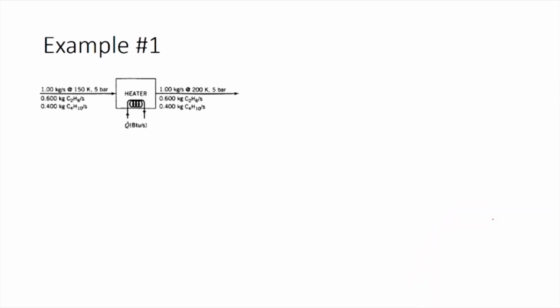This is an open system, which means the energy balance for this system would be ΔḢ plus ΔĖk plus ΔĖp equals Q̇ minus Ẇs. For this system we have been asked to ignore kinetic and potential energies. So, these two will go to 0. There are actually no moving parts in the system like a piston. So, therefore, the shaft work would also be equal to 0.